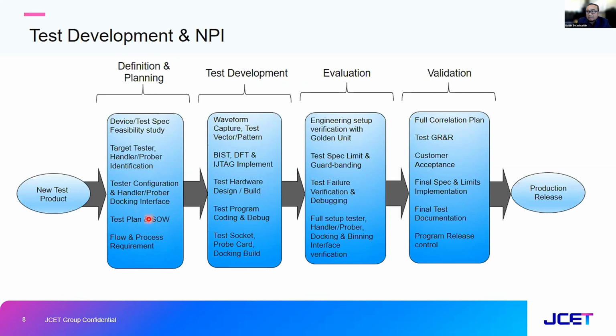And also probably OSAT will request you to come up with the statement of work. That's a kind of mutual agreement between the OSAT and the customers to work together on what to achieve, what to hit on the objective for tests. Then from there, as a collaboration between the customer and OSAT, we'll go through this test development that includes all this understanding of whatever you have put in your test plan, that includes this DFT strategy, and also, if you already converted the test program, test vectors or test patterns, that will be a great help to the OSAT. But some OSATs, like us, also offer test pattern and test vector capture.